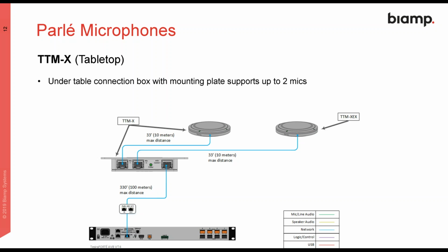Can we use this as a replacement for the Sennheiser tile mic? Yes, if you want. They don't use the same connection though. How many AEC reference channels? So again, one AEC channel per mic. Can I have more than 2 mics on the AVB network? Yes, you can have 2 mics per network box, but you can have as many network boxes as you want, each of them with 1 or 2 microphones.